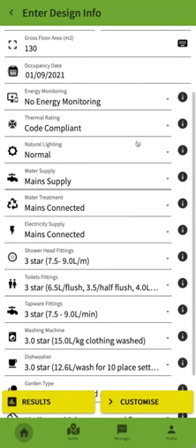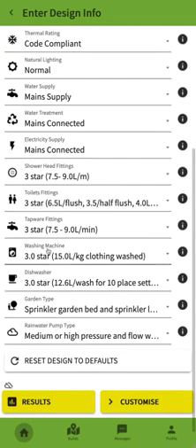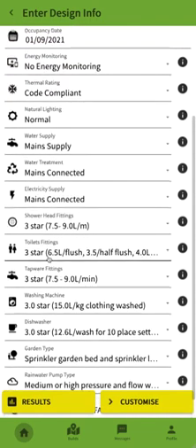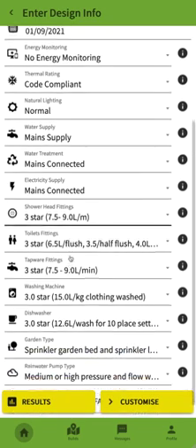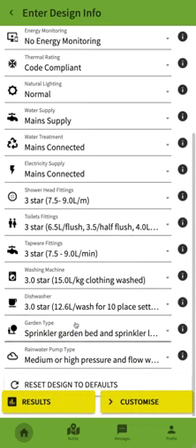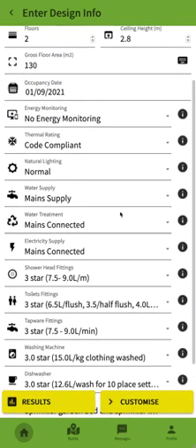I've got a heap of building attributes. Some of these are a bit of a deep dive, but are necessary because there might be some kind of feedback loop. For example, all our water use needs to be decided pretty well up front, because all our fixtures and fittings determine the amount of water available for a grey water system to then supply back to irrigation, and that relies on understanding how much water is going to be used in the building. So that's one of the areas we need to deep dive a bit on here.